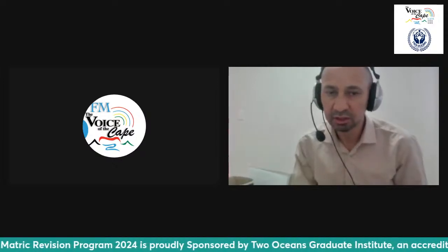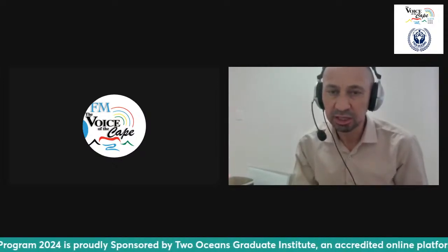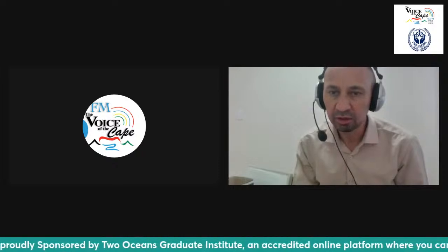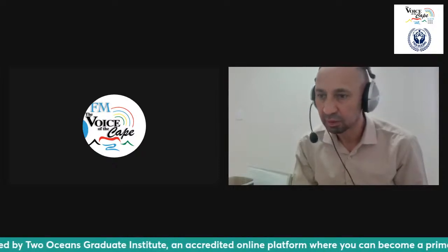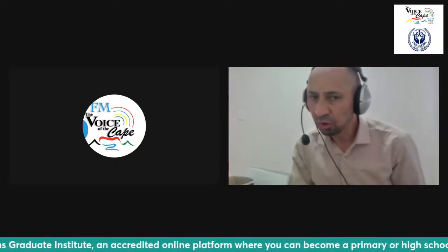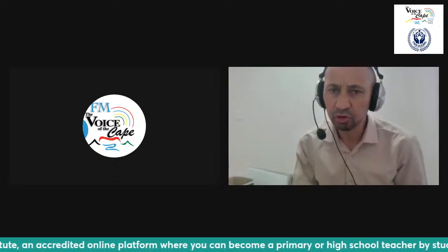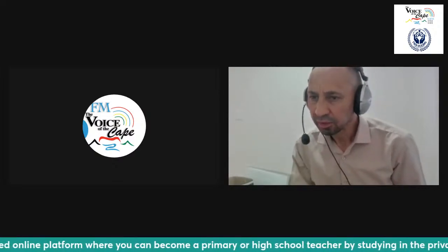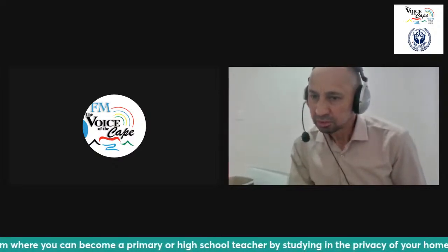For every 30, that distance from here to here is 10, 20, 30, 40, 50, 60. And then you obviously have a scale of 1:1 on top here. And then you need to label the displacement graph and include the rotational scale. So it's important for you to label the graph here, cam displacement graph, and the scale of 30 equals 10. And for that, you get 2 marks.